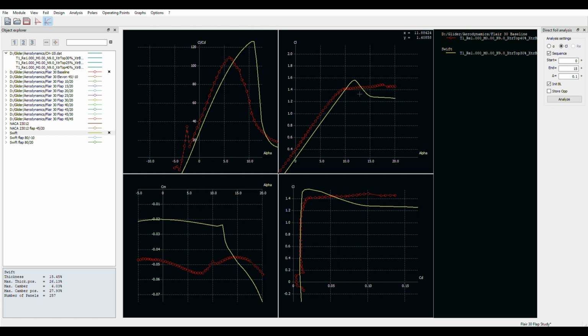All of this analysis is for 2D airfoil. It's as though the wing is infinitely long. It's the maximum performance that you'll get out of the airfoil. So it has a fairly sharp stall, drops off, then plateaus off. Typical stall curve, other than the fact that it's a little bit sharp. But we don't really worry about that because an airfoil is not a wing. I'll say that again so you always remember it. An airfoil is not a wing. You're looking at airfoil data, you're not looking at a wing.